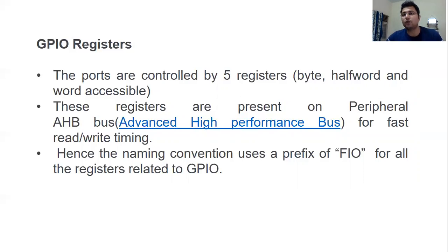But apart from that, if you have to use it for some specific purpose like UART, PWM, ADC, those are all things we will use later on. For that, to configure the function, we have to configure the pin select register corresponding to the particular port and its particular pin. That is all about the pin select registers.